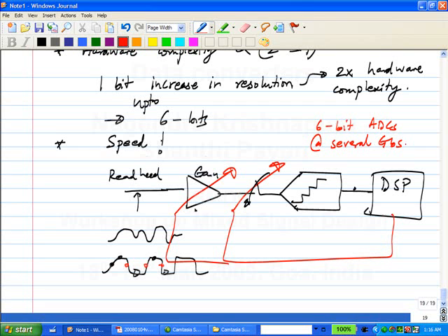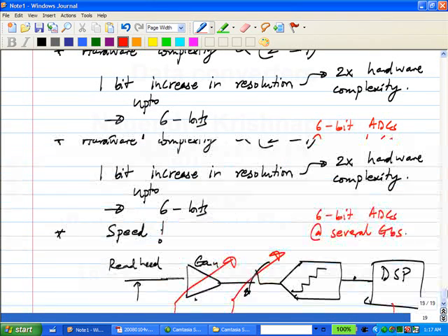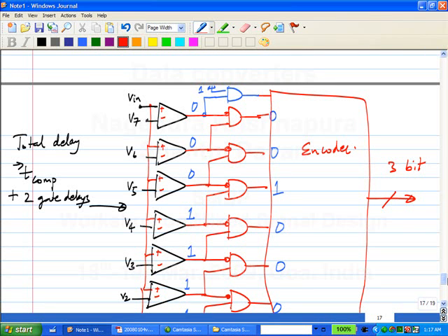Okay. So, is the sampling rate then only to optimize the VLSI? Oh yeah, of course. So from an architectural level, a flash converter is a very simple thing. It can't get any simpler than that, right? We have in fact figured out everything else except what? The encoder is combinational logic. It's straightforward, you have gates. The only thing we need to figure out is how to build a comparator, a block which will compare two inputs, and obviously there must be some trade-offs involved. Whatever you try to do, you always find that you can't do as good a job as you want. So there must be an understanding of what non-idealities there are in the comparator and how they affect the performance of the converter.